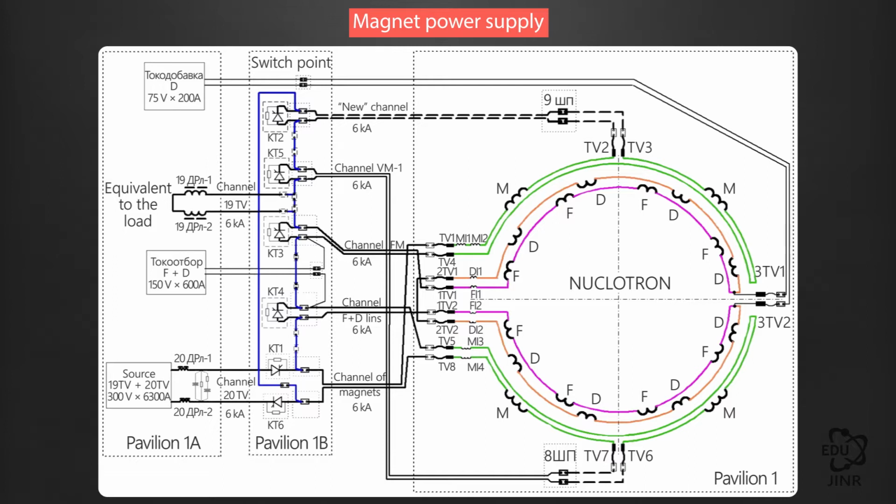To provide the required beam focusing, there are 2 additional supplies of lesser power, one of which performs the partial current removal from the successively turned on focusing and defocusing lenses, while the second applies additional current into the defocusing lenses. The main power supply provides current from 60 to 6,300 amps, with voltage of up to 300 volts. The rest of the power sources have less power.